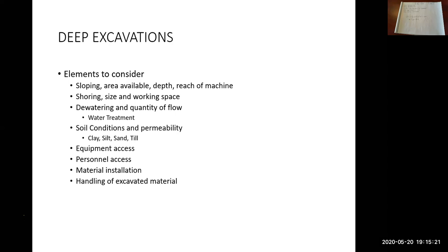So other things to consider are the depth of the excavation. Do you have an excavator or some type of digging apparatus that can reach the bottom from the top? Or does your excavation equipment have to be in the hole?